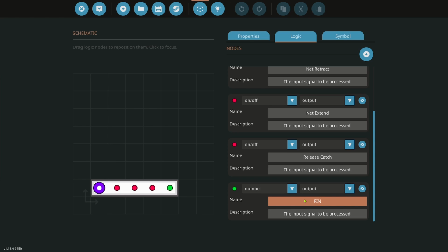I like to use fins. The reason is they're very light. They're going to cause fewer problems if, for example, you're trying to pick up a big heavy net system, which might cause your boat to list. People may want to put this on a small boat. This tends to be pretty light, so that's why I like to use the fins. And we're actually using the hydrodynamic forces to stretch the net, not just using weight and mass. All right, so real simple there.